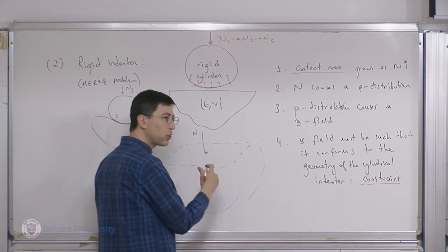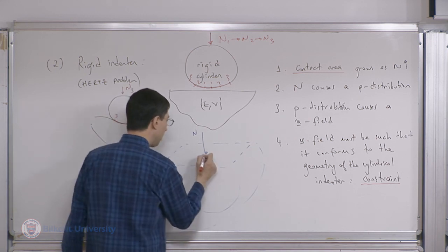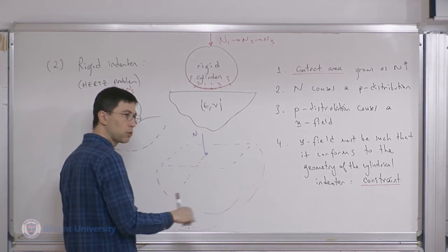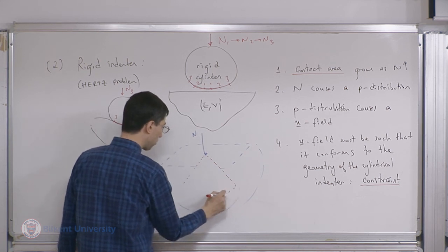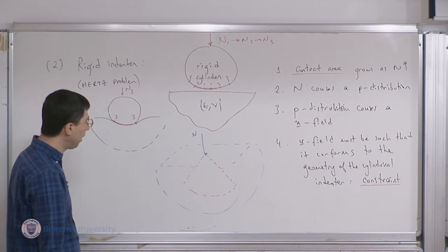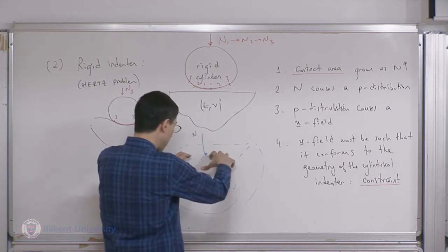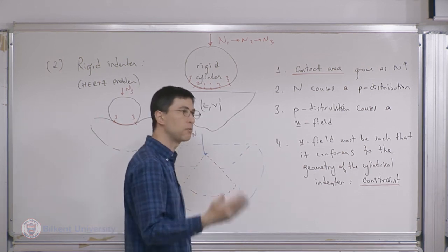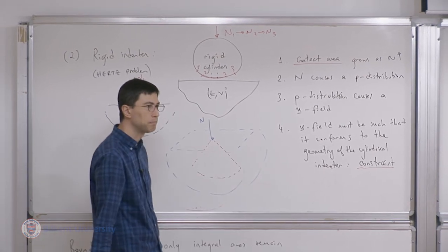And when I try to argue about the decay of the stresses, I don't remember the details exactly, but I suppose I would argue not along the surface of a semicircular region, but rather on the surface of something like a cone, okay? And by looking at the equilibrium, I would deduce something about the stresses, how they should decay, because the integral of those stresses should be statically equivalent to a force. I would say something about the Airy stress function and proceed slowly, okay? And there's a solution for that as well. Okay.